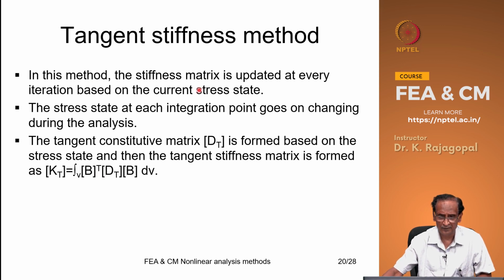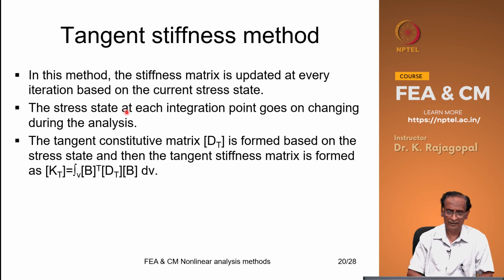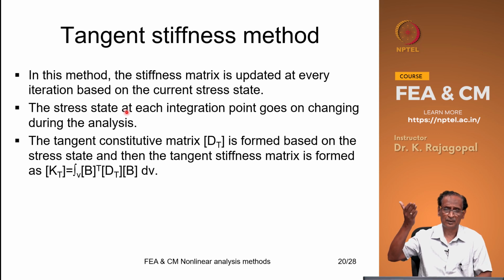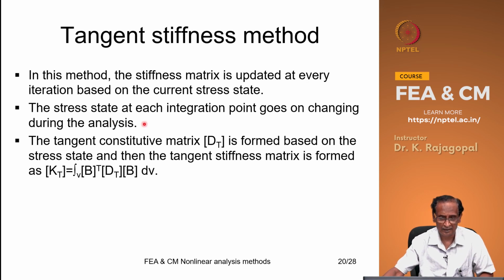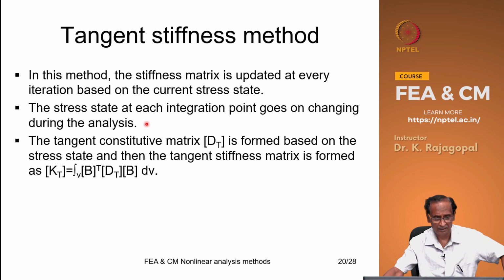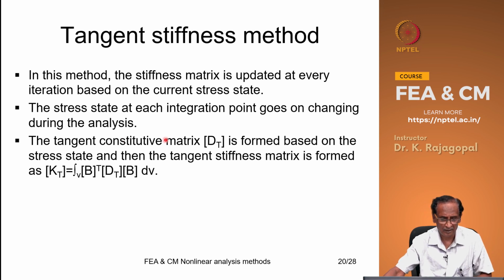So, in this method, the stiffness matrix is updated at every iteration based on the current stress state, and the stress state at each integration point goes on changing during the analysis, because as you apply the loading, you will have some deformations, and these are different at different elements. So, at each integration point we calculate the stresses, and then form our constitutive matrix Dt,